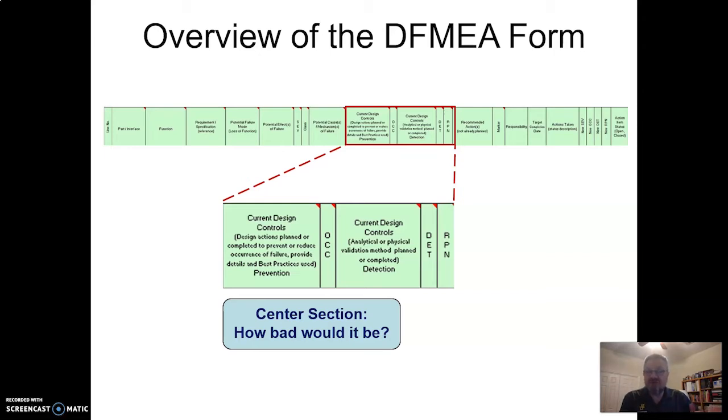So flipping back to the talk we did on the GM ignition switch, if the issue is a customer convenience issue, something the customer doesn't like, it causes an inconvenience, but it's not safety related, that would have a lower severity in the DFMEA. It doesn't necessarily need to be addressed. It's good if you can address it from a standpoint of doing well in the market and satisfying your customers. Whereas if it comes to light that the problem is safety related, then it must be addressed in the DFMEA.